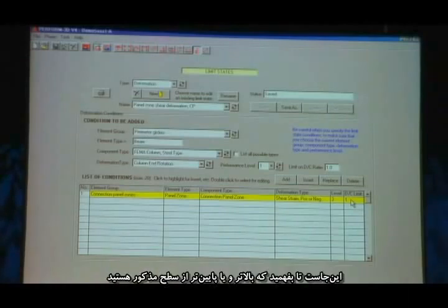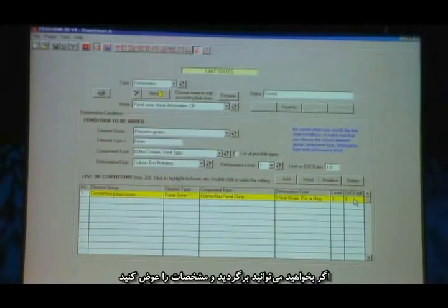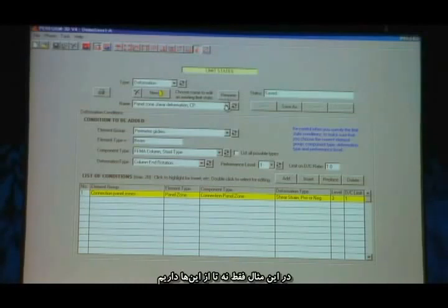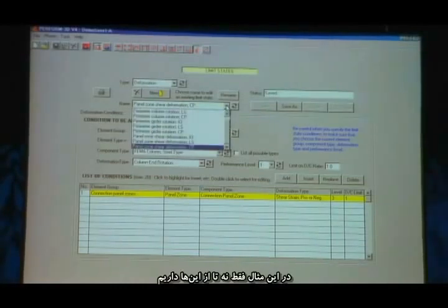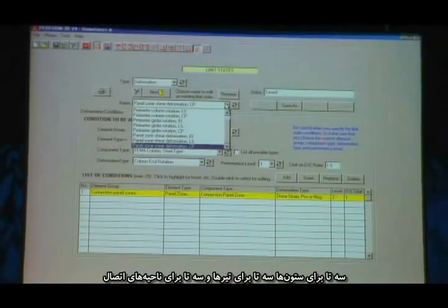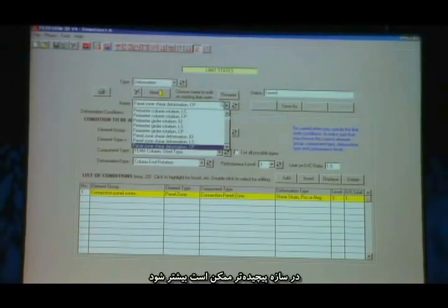This enables you to adjust things up and down a little bit if you want to without going back and re-specifying the properties. And so there are, in this case, only 9 of these things, 3 for the columns, 3 for the beams, 3 for the panel zones. In a more complicated structure, it could be many more.